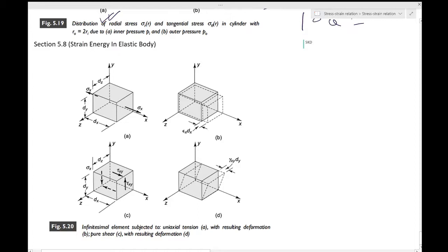So we had introduced the concept of elastic energy using springs and uniaxial member. In this chapter, we want to extend this concept of elastic energy to arbitrarily linearly elastic bodies which are subjected to small deformations. So you no longer have one-dimensional springs or uniaxial members. You have this three-dimensional body with all the bells and whistles of stresses, strains in 3 dimensions, and you want to now find what the strain energy is in this body.